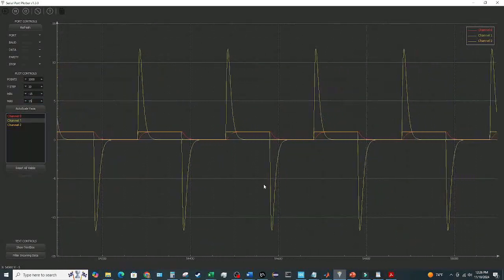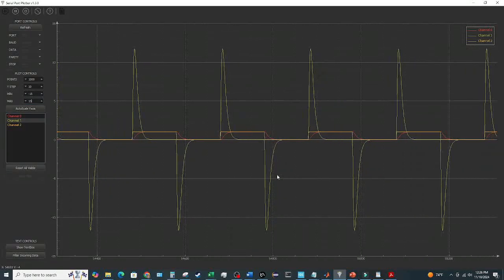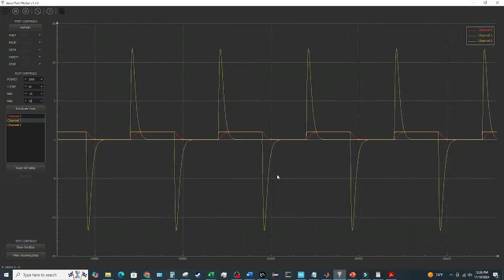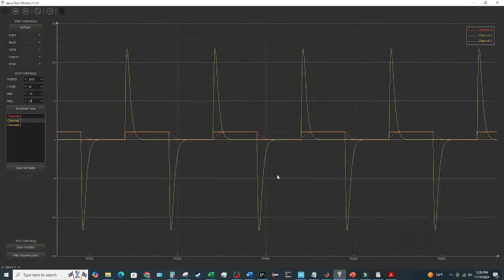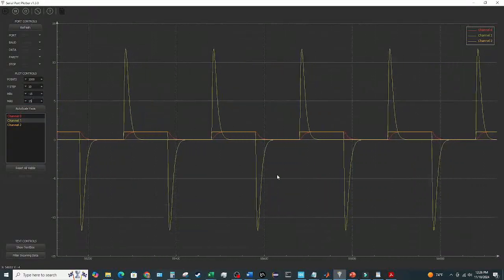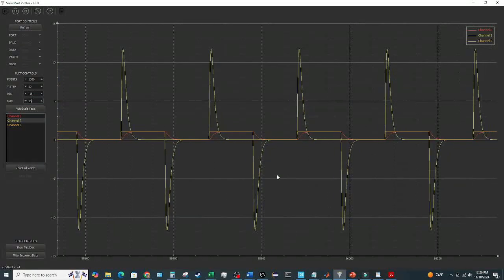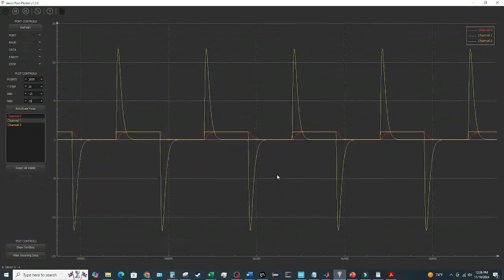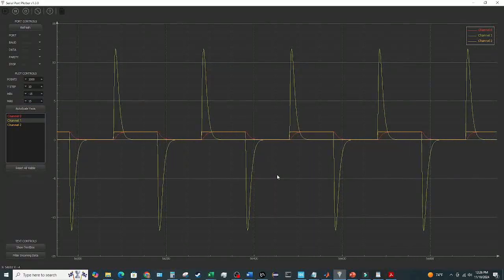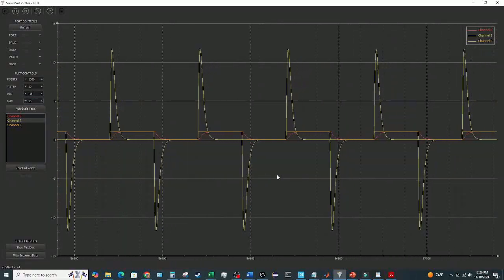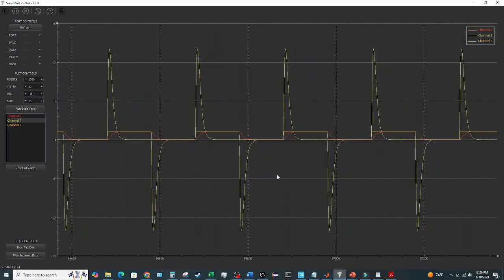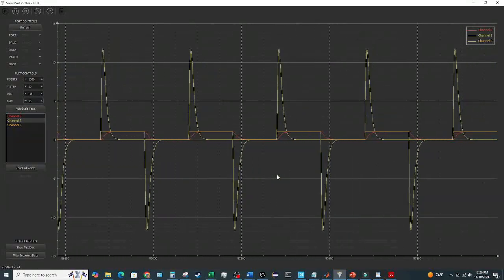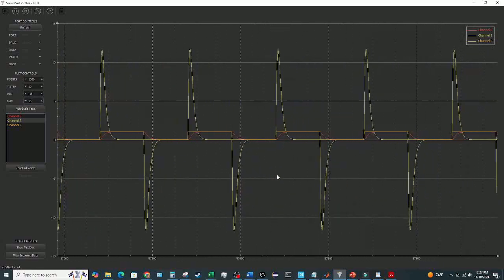So anyway, there's an example of how to implement a second order control system in an embedded system, or simulate the second order response of a system in our embedded microcontroller, using this serial port plotter application, which I think is a really good, easy way to just pull data out of the microcontroller using printf, not having to use a scope. Pretty reliable way to plot real-time data.